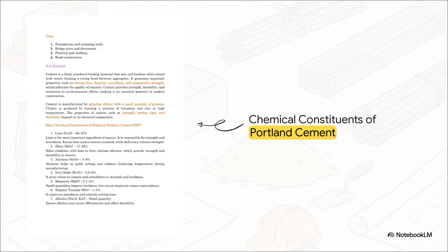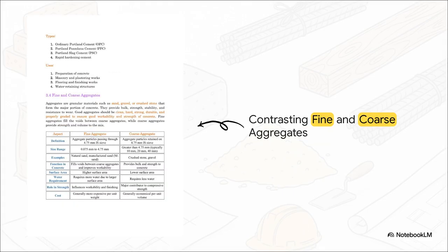These are strict industry standards, and they are strict for a very good reason. So that's the glue. Now let's talk about the skeletal bones, the aggregates. We separate fine and coarse aggregates using one very specific standard, the 4.75 mm IS sieve. Picture a standard kitchen colander.